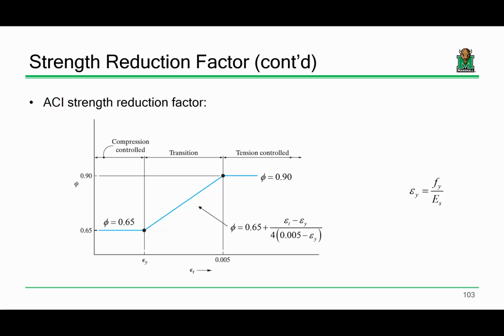So the tension-controlled section would make the steel want to deform before the concrete. Yes. Instead of the concrete just giving in, the steel's going to go first. Exactly. And so you've got a lot of warning before failure. I mean, there's a point, like once you hit 0.85 f'c in the stress block of the concrete, and fy in the steel, the beam's gone. But at least you knew it was coming. This is good stuff. This is really good stuff.